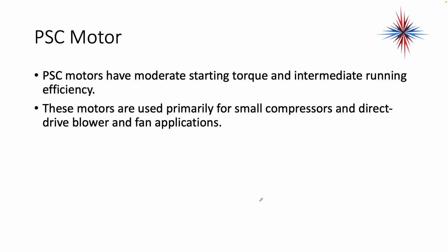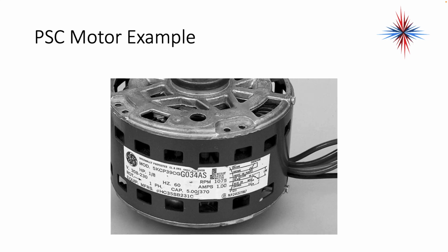The PSC motors have moderate starting torque and decent, or intermediate, running efficiency. The motors are used primarily for small compressors, direct drive blower, and fan operations. This is an example of a PSC motor.